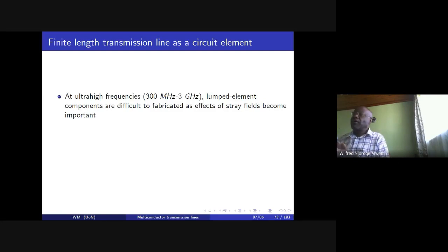And that length of wire will introduce those transmission line characteristics. Therefore, in the end, we'll no longer be seeing a pure resistor, because the positive side and the grounded side are at different potentials, there will be a stray capacitance developed across the resistor.